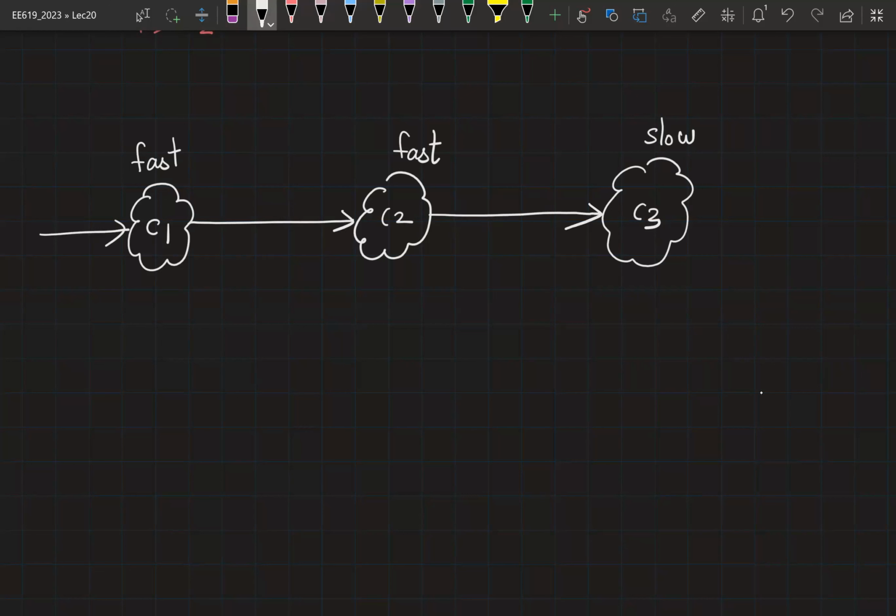This is also going to come immediately. But C3's output is going to take a long time to appear at the output. Now, in this case, there is a problem of how to arrange the inputs, right? Because let's say C3 was processing the previous input and it required this value to be stable here. But because C1 and C2 are very fast, it might appear and correct the data here very quickly, right? What is a possible solution now?